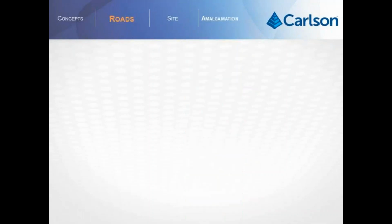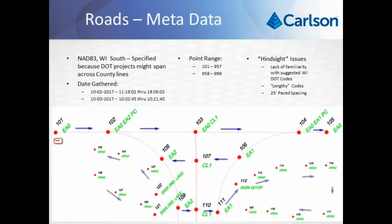So let's begin. As we're working through this particular site, one of the things that I wanted to do was collect it efficiently. As I started with the entrance road in shot number 101 up in the northwest corner, I decided to code that with an edge of asphalt 0 code. And one of the things that I decided to do with this was utilize the Wisconsin DOT feature code library.